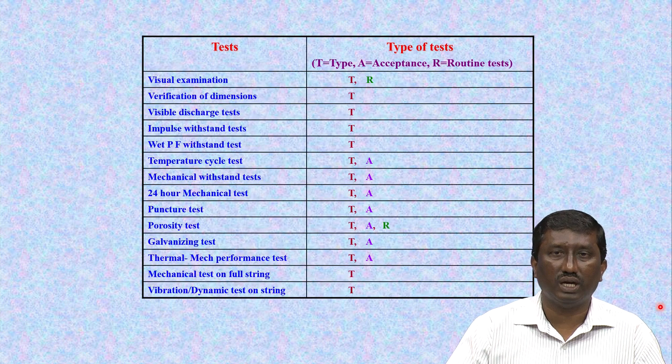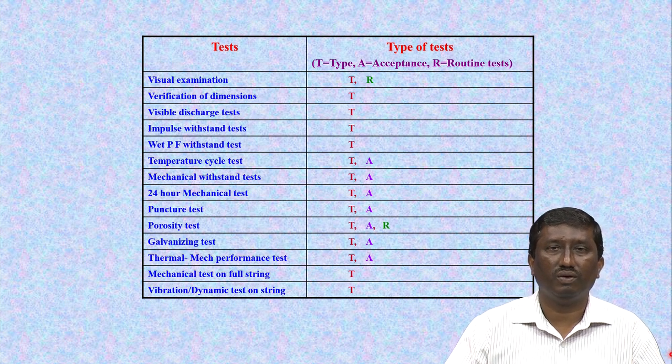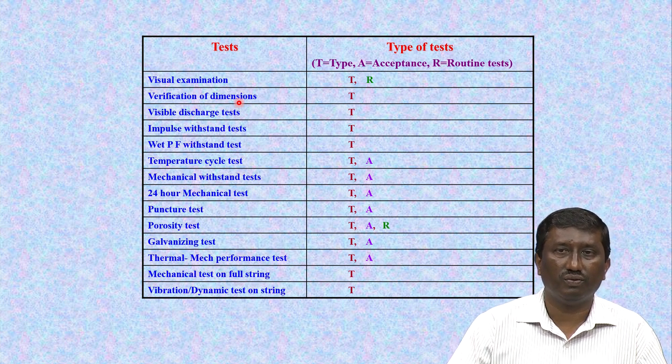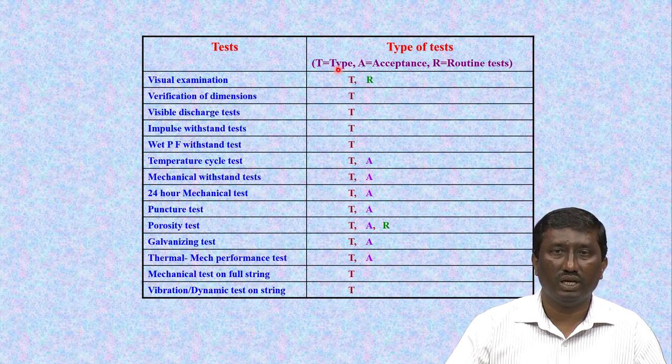So, this chart gives an idea of the various reliability tests which have been prescribed by the standards. So, you can see the two columns here, the requirements. I was mentioning the different types of tests which are carried out for the reliability of any equipment. So, we have three types, that is the type test, the second being the acceptance or the sample test as we call it, and third being the routine test.